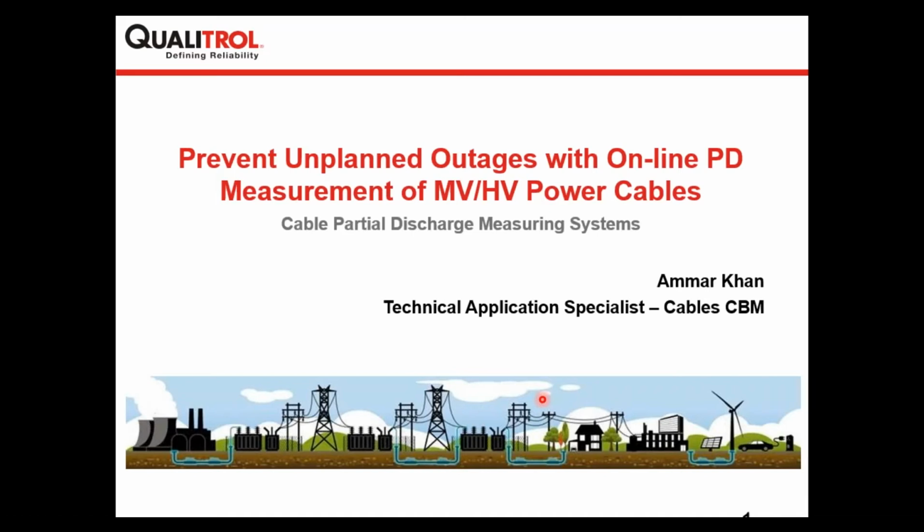Yes, this is a very good question. The water trees are formed because of the impregnation of water in the cable insulation in the presence of field. So when these trees are filled by water, they will not give any partial discharge in the power cables. But there is another argument. If you read the literature, different research papers, there is an argument that when these water trees are dried out, they can lead to partial discharges.